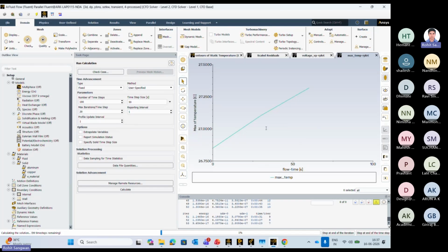Can we simulate water content having two plates of terminal cathode and anode? Want to check bubble formation? Yeah. Not only the battery model, we have to use more in this. When we have bubble water also, then instead of the battery model we have to go with the potential electrochemistry model because we are working at the electrochemistry behavior. You have to use the potential electrochemistry model. You can check in the theory background of the potential electrochemistry model.